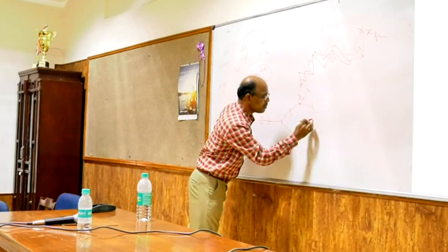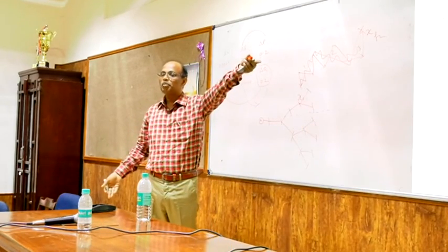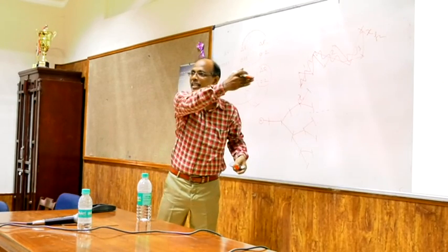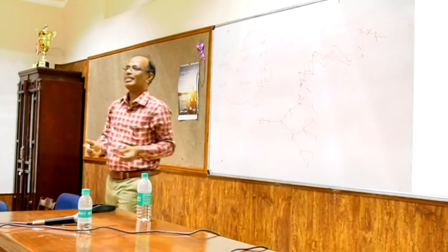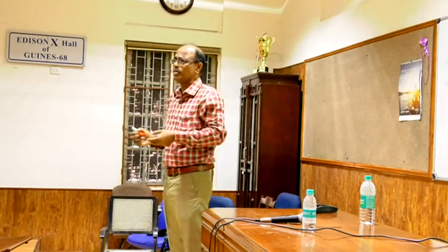It grows. These are all the extensions. So say for example, Anna University, if some developer proposes another nagar nearby, then there will be a radial feeder, right? So it grows in this way, grows like a tree. So in general, distribution systems are radial in nature. This radial nature itself causes problems in the solution process.